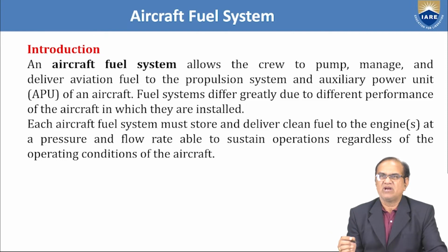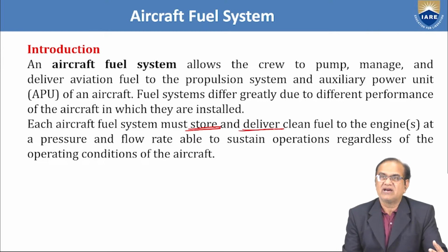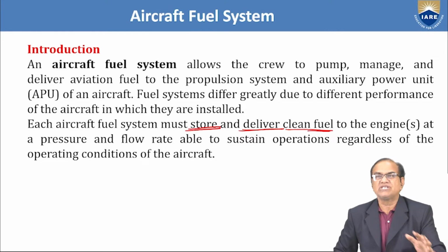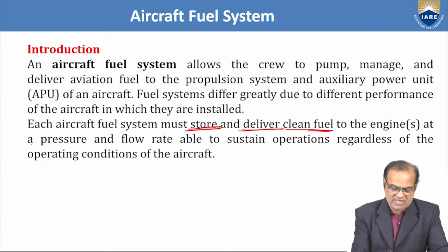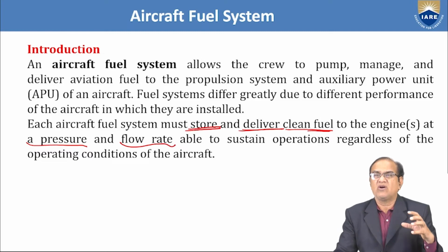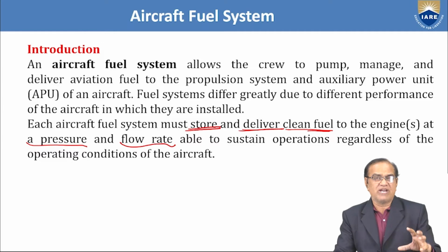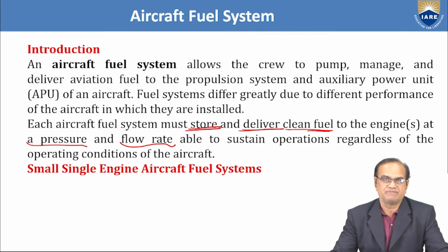So for every fuel system, the first thing is that it should be able to store a sufficient amount of fuel, and it should also be able to deliver clean fuel in all operating conditions of the aircraft. These are the two things any system has to do. It also ensures that the required pressure and the required flow rate are maintained in whatever conditions. These are the requirements of the system.